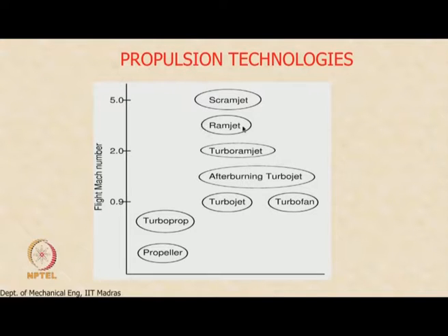So, for sustained supersonic operation, we use the ramjet part of the engine, and for takeoff, landing and reaching cruising altitudes, we use the turbojet part of the engine. In contrast to the afterburning turbojet, the turbo ramjet can actually cruise at supersonic Mach numbers for a sustained period of time, whereas the afterburner can only attain supersonic speeds for short durations of time.